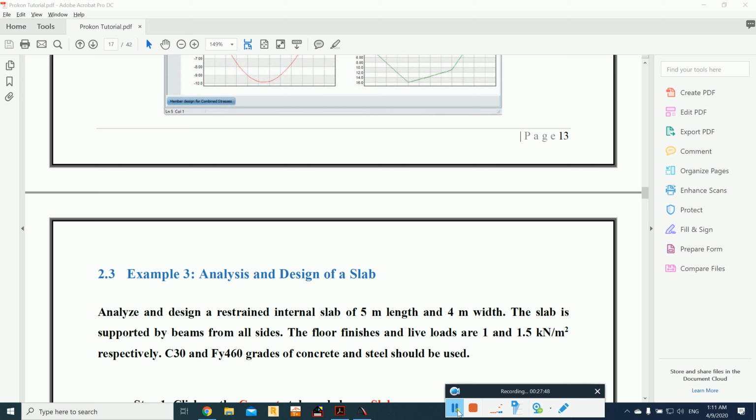Now the other type of connection in terms of two-way slabs, since this is a two-way already, because the longer dimension, which is 5, divided by the shorter dimension, that's 4, is going to be less than or equal to 2. So the other support is a simple support, and that can be represented by having a concrete slab supported by steel beam.